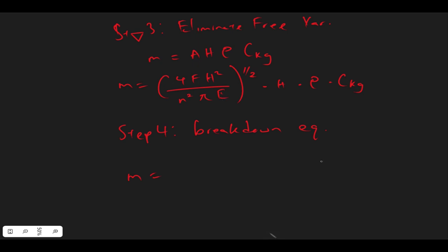So you bring out all the material properties as density times C divided by Young's modulus. This Young's modulus has this square root, so E raised to power 1 divided by 2. So next you now bring out your geometric constraint. The geometric constraint is the height h. So h here and h here, the half will now cancel the squared. You now have h squared.